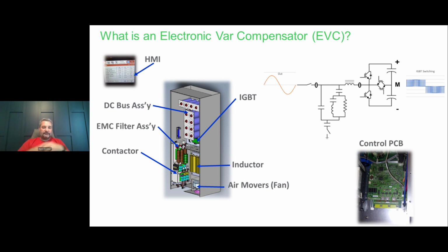And what they're doing, they're using power electronics. It's basically IGBTs with a DC bus. It's very similar technology to a solar inverter or UPS, but used to inject reactive current and negative and zero sequence current to rebalance the current on the network. So you have your IGBT switching, which is pulse width modulation. It's being filtered or cleaned up by an internal filter, and what you inject is this current waveform on the network. In this waveform you can have balancing current, and also leading or lagging VARs that you can inject.